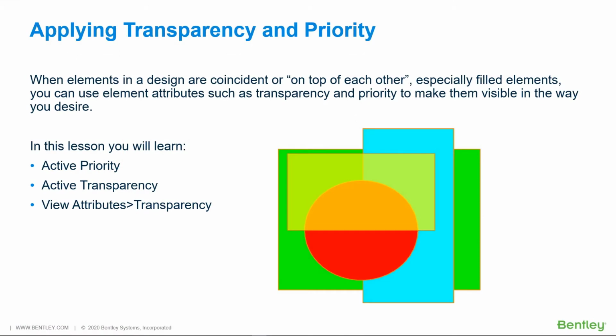The element priority value may vary from -500 to 500. The elements assigned to the highest element priority are displayed in the front, while the elements assigned to the lowest values are displayed in the back. Note: transparency, as well as display priority, can be applied to any drawing elements, as well as levels and references.